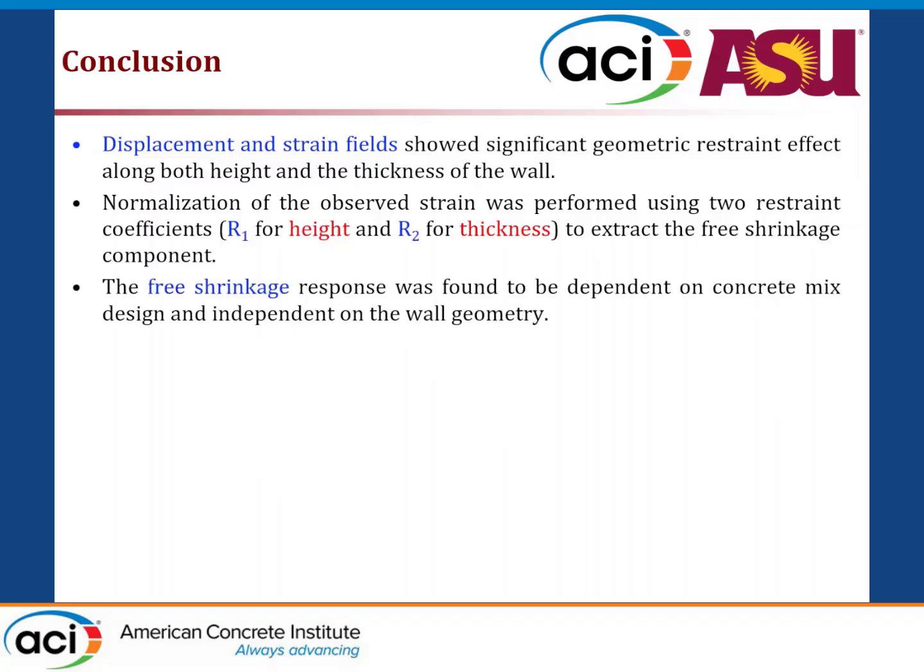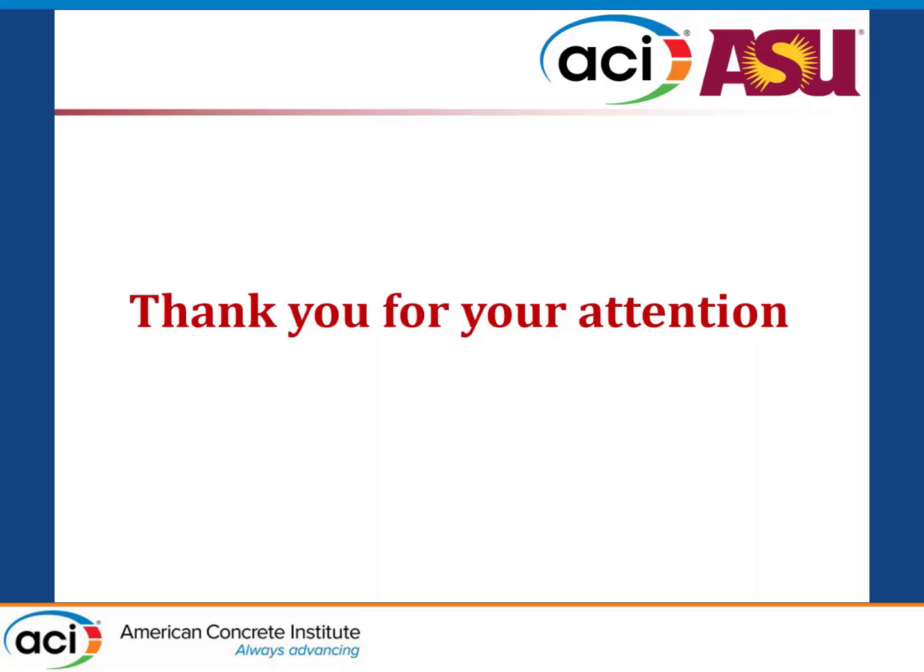But this is a general idea of how you can understand the typical shrinkage behavior in printed samples. We are working on finding actual values to show the free shrinkage of these printed elements. The problem is that we are facing a few issues: if you print a single filament, it starts cracking right away because of the environmental exposure condition. Everything is in a lab environment with 25 degrees Celsius and about 45% relative humidity. So we are working further on defining shrinkage properly in terms of mix and water content. We are trying to come up with a more detailed explanation on this.